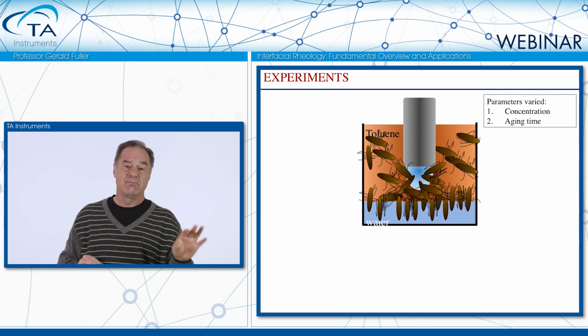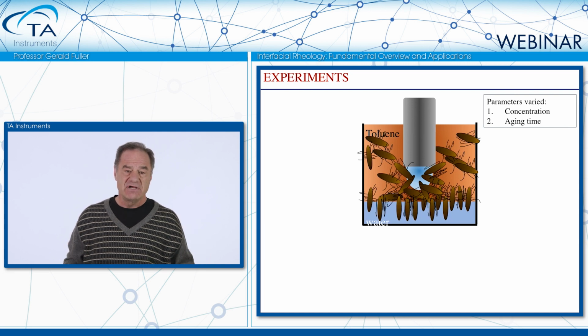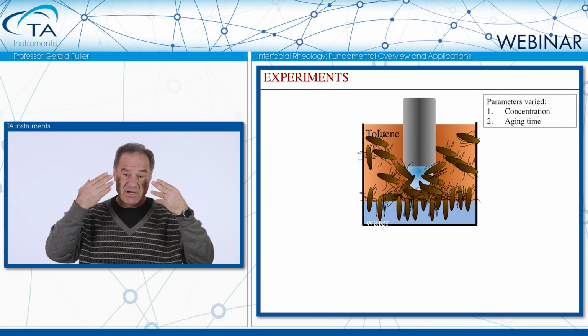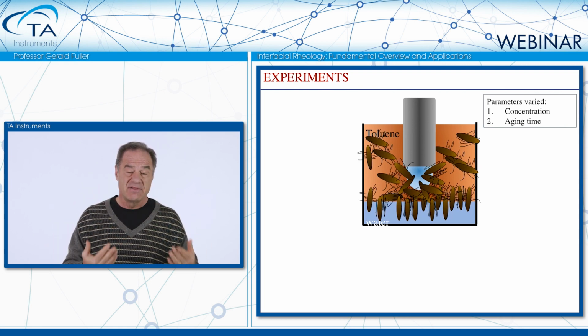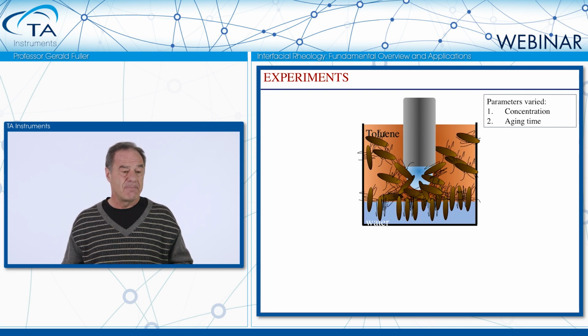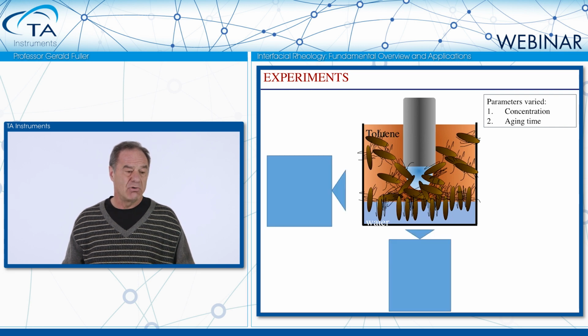This is a thin film problem. In fact, most applications where interfacial rheology is important are thin film fluid mechanical problems, like in the tear film of the eye or in the lung. Thin film hydrodynamics. So we would like to then see how long it takes this drop to coalesce.